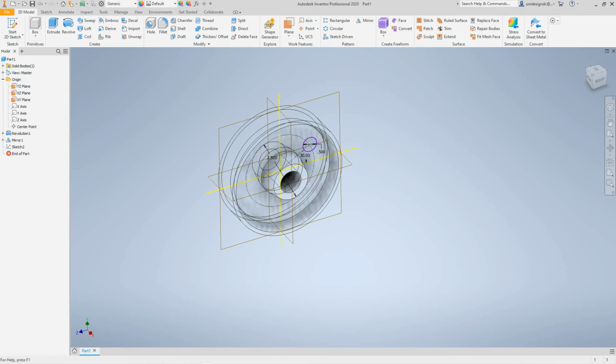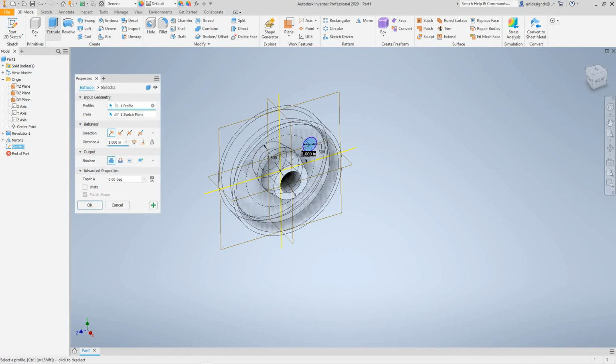Okay, we want to finish our sketch. We go to 3D box. I'm going to hit extrude for this guy here. And this one will go through. And then we will set, what else we need to set in here? This is a cut.